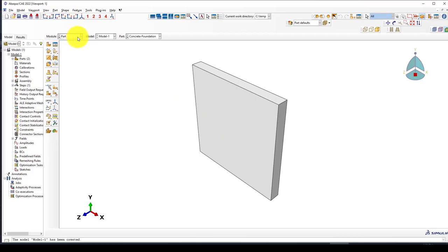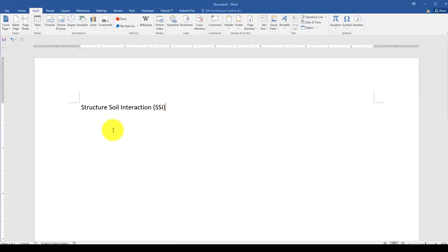The next is the beam column section. Here I'm going to give the beam. The beam section I use is a box, which is 300 by 200 by 20. So the height is 300, the width is 200, and the thickness is 20 millimeters for the entire structure.